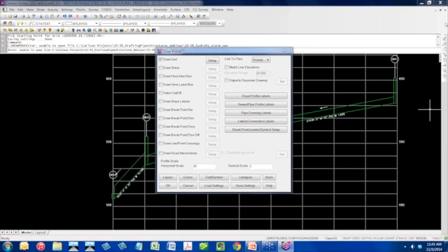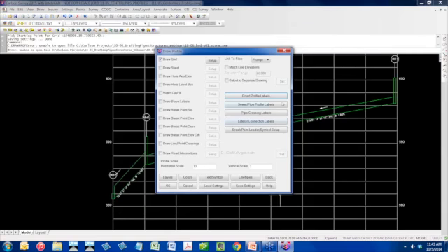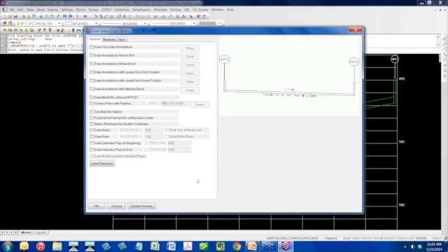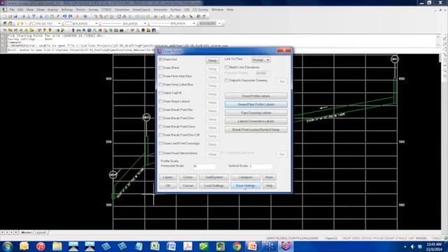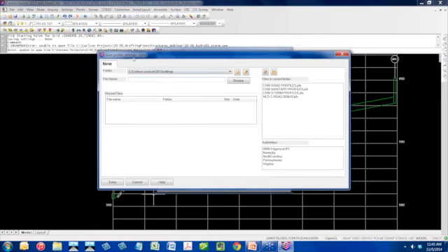So the last thing that I want to mention here are the all-important buttons of load settings and save settings. I've mentioned a few times that there are thousands of little options in these boxes. Once you take the time to get all those thousands of options set just like you like, you get all your road profiles set up and they're labeled just the way you like them, and the sewer pipes are just the way that you like them, you'll want to hit the Save Settings button here. And this will export those profile settings as a PFS file.